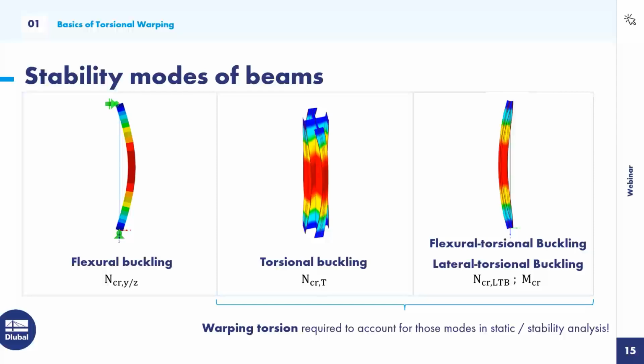Because only with 7 degrees of freedom, the kinematics of the beams loaded in bending, axial force, and torsion are properly taken into account. And I want to show you another example where this is quite important, and it is not related to this case of torsional stability, but it's maybe a much simpler case that you and I would probably stumble over in irregular analysis.